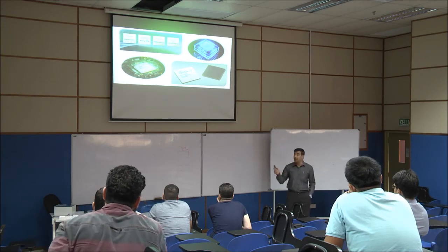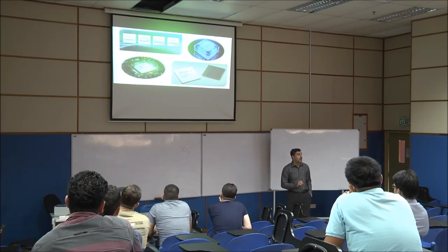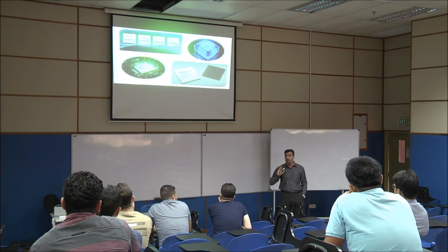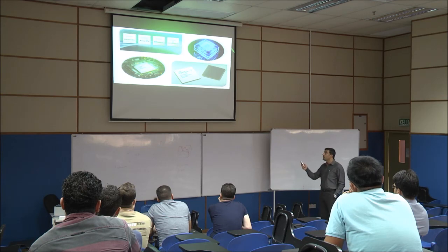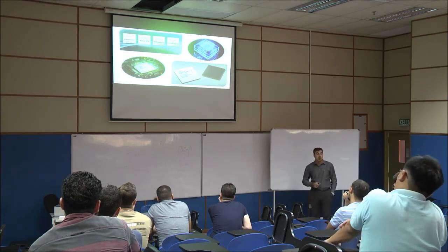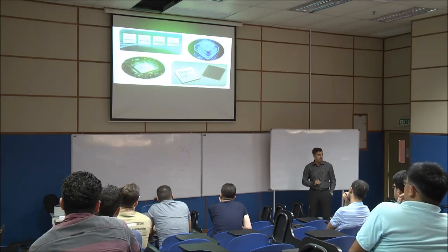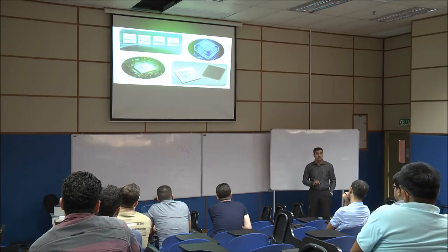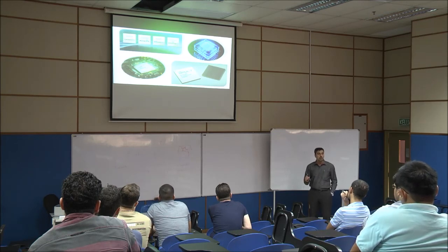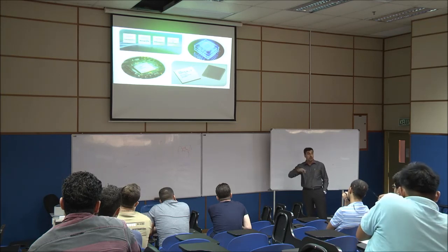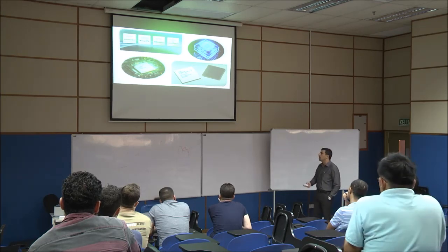Okay, till now there are already 5.5 million logic elements inside. In addition, for all this, I already explained to you things like memory, DSP components, cores, hardcore, and so on. Clear? So this is one. Which one? This is what we call a three-dimensional design architecture inside your chip. Clear? So I will show you later on. Stratix 10 is already three-dimensional, not just one dimension, okay, of projection. Then we will see in a few slides.